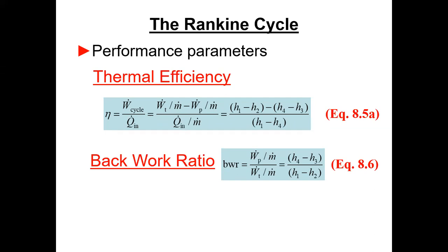We're pumping water. And so you put water in a pump, you don't have to put all that much energy in to increase its pressure. Brayton cycle is trying to move a gas, trying to compress basically air. And that's a very inefficient process, increasing the pressure on a flow of a gas compared to a liquid.